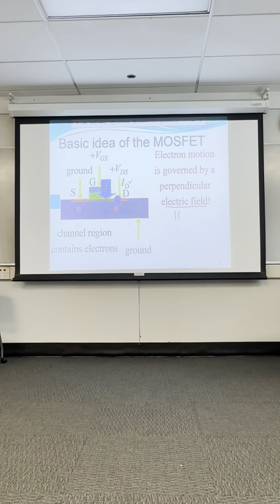We're just getting a basic understanding of what conditions have to be there for this transistor to actually become an amplifier. So the drain current is controlled by the gate to source voltage. And the authors drew one of the curves showing the gate to source voltage versus the drain current.